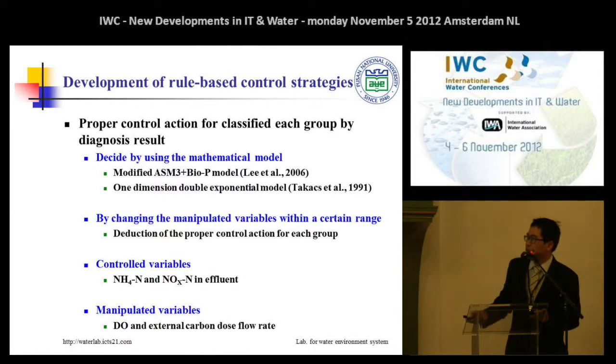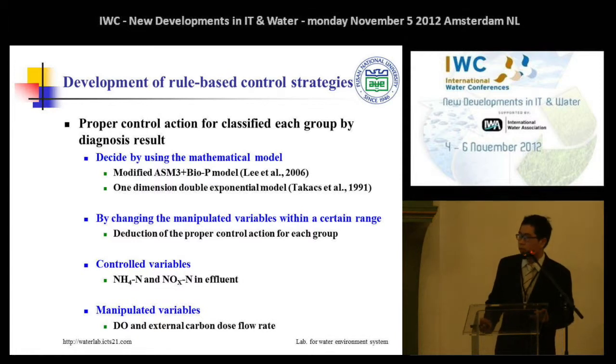In this study, the controlled variables were ammonia and NOx in effluent, and the manipulated variables were DO concentration and external carbon dose flow rate.